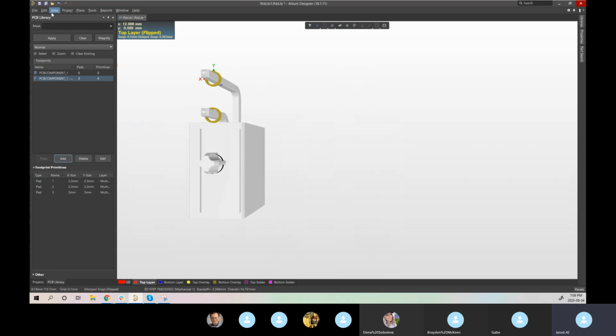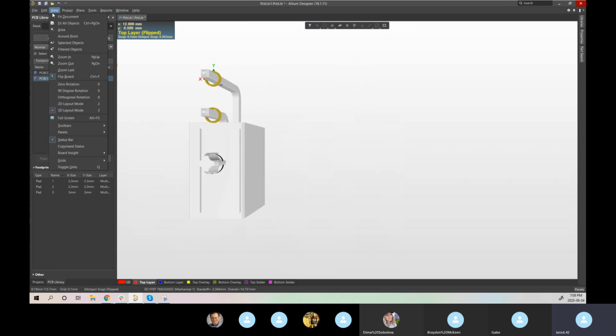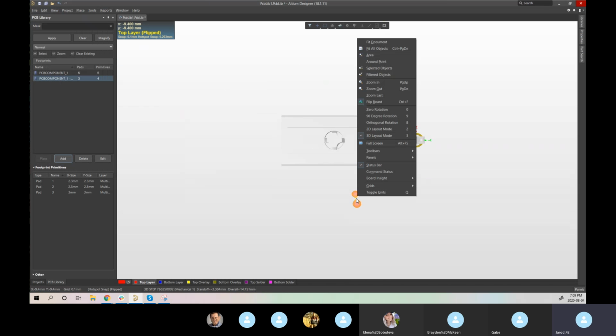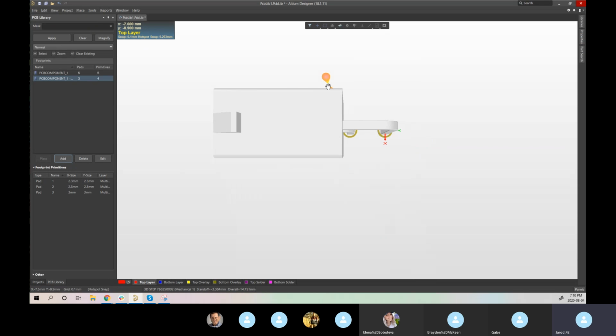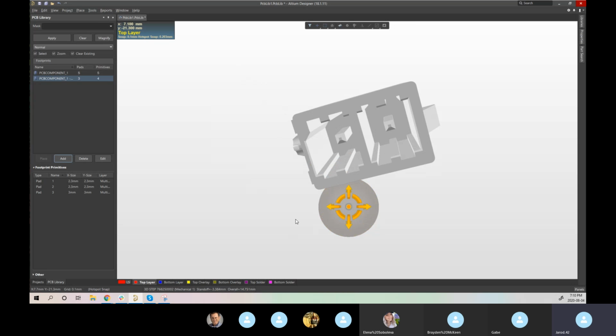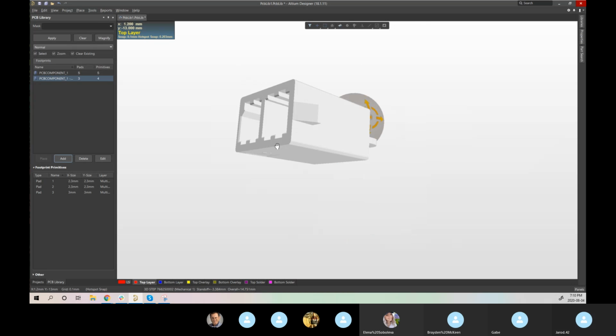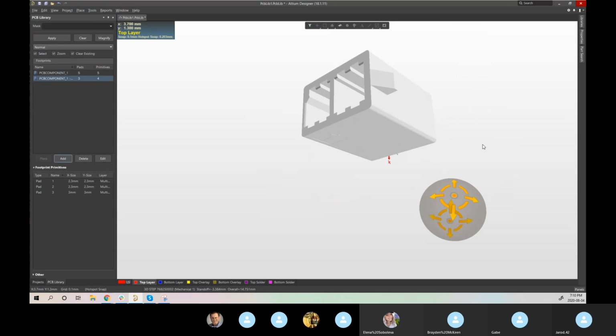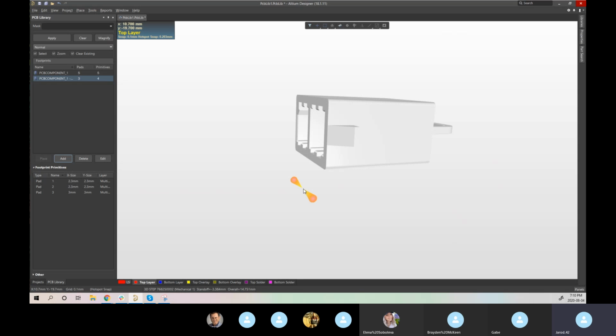V, B, or what is it, view, or here you can see the 90-degree rotation, the orthogonal, so you can do all of these rotations, or just V, where B just does a full flip around, and then shift and right click drag is how you can manually look around at it, just for anybody wondering how I'm moving it around.